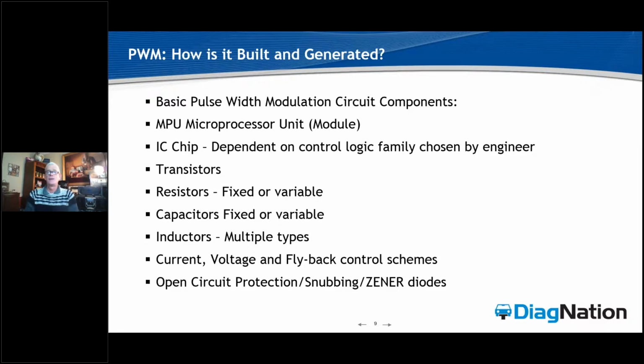Flyback is the voltage and the current that is thrown back at the driver of the circuit that's being operated. For example, an ignition coil, an injector, or a fuel pump module, or a Valvetronic motor, or something of that nature. And that reflected energy is what literally takes out the driver and destroys the inside of the PCM. So we'll touch on that a little bit to understand how to look for that flyback on a scope.